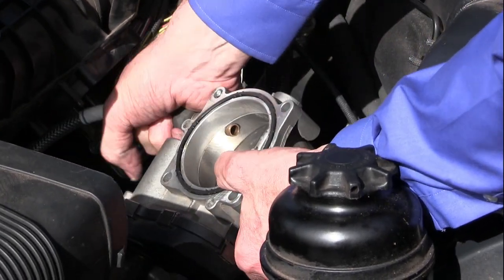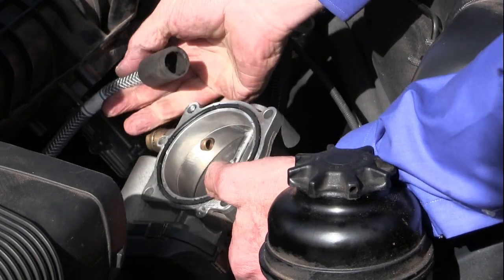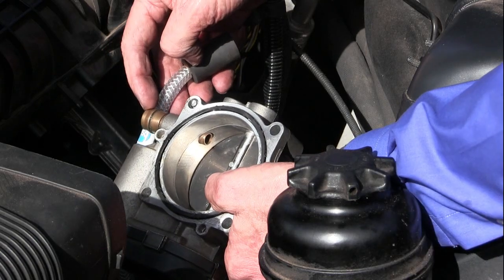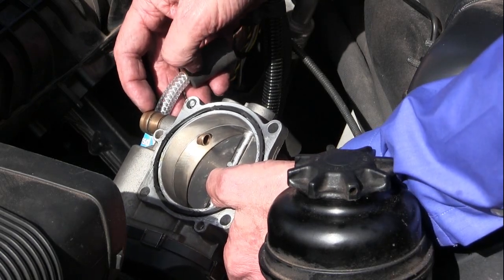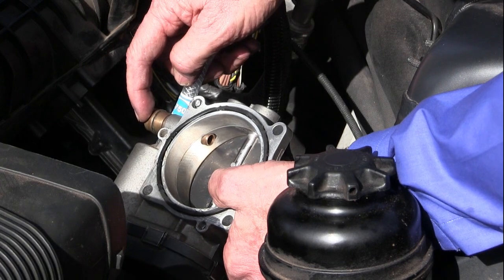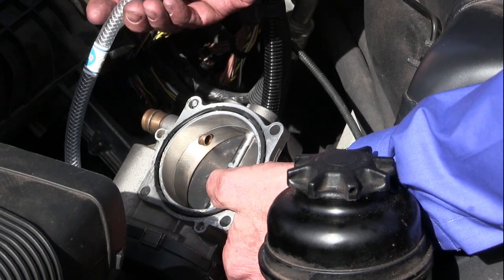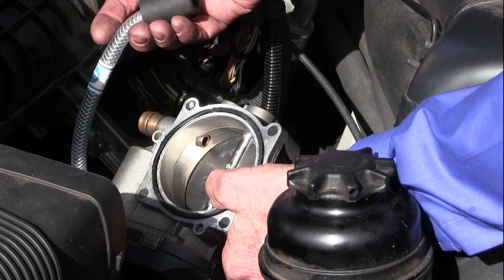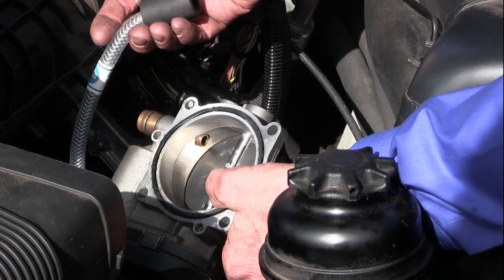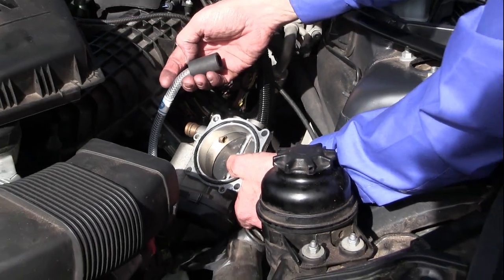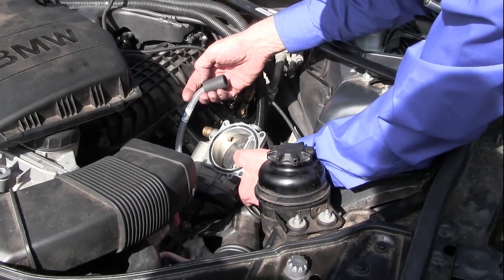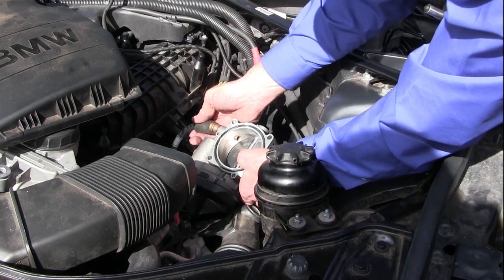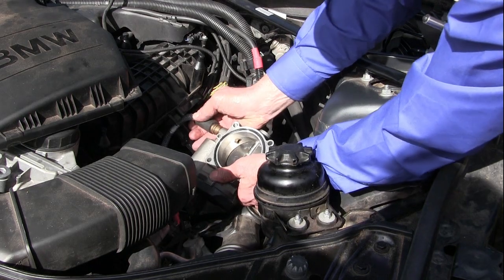I want to make a point that the only place that the ATS hose is ever attached to is the port on the induction system. You would never use an interim hose between the port and my line. What will happen is that will cause the chemical to fall out of the air, puddling in the motor. This would either cause catalytic damage or engine damage. You only use the hoses supplied by ATS, and they must be put directly to the port.